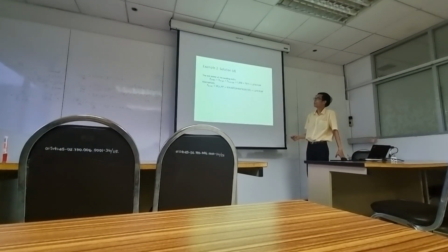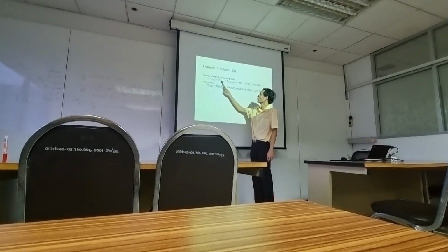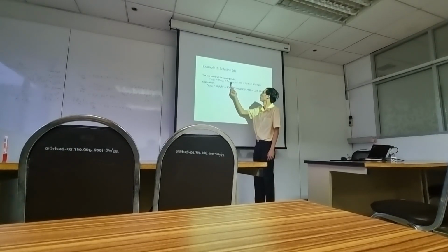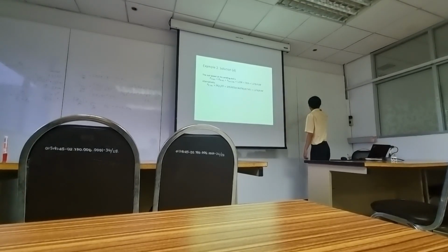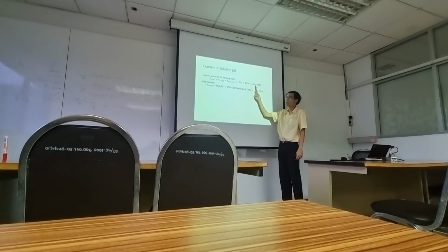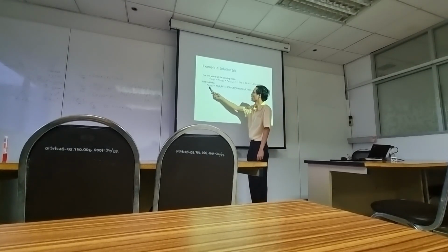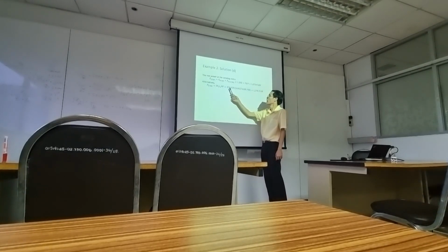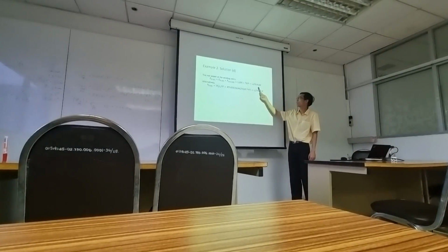The last one is the real power at the sending end. Power at the sending end equals power at the receiving end plus the loss. So this is the load power. Power here is 1200 plus loss. You get the power at the sending end. Or you can use this equation: PS equals 3 VS IL and then the power factor. So 3, this is VS, this is IL, and this is the power factor. You will get the same result.